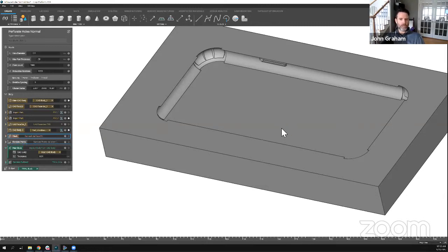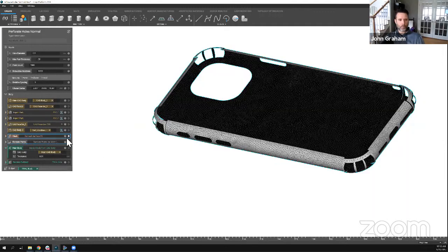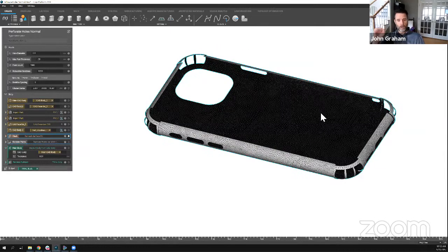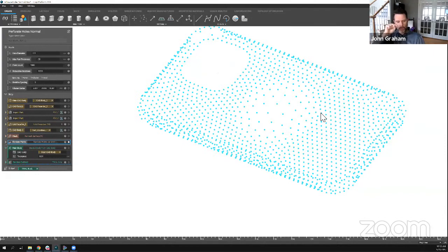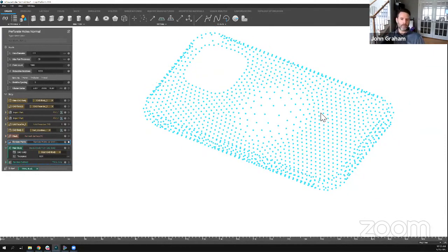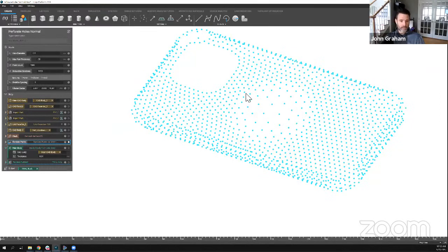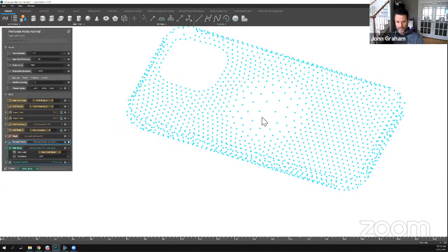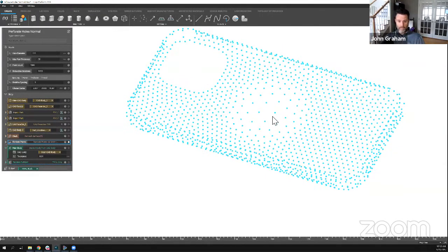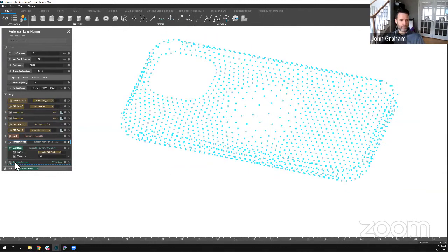The surfaces on which I want the holes, well, I've just turned those into a mesh. Why did I do that? Well, that mesh body is going to turn into a series of random holes. Each and every point is going to represent one of the holes on the body. So where I mentioned the logo would go, you don't see as many points there. I could certainly drop this to 0 if I wanted to, meaning 0 points, but I don't think I want to do that quite yet.